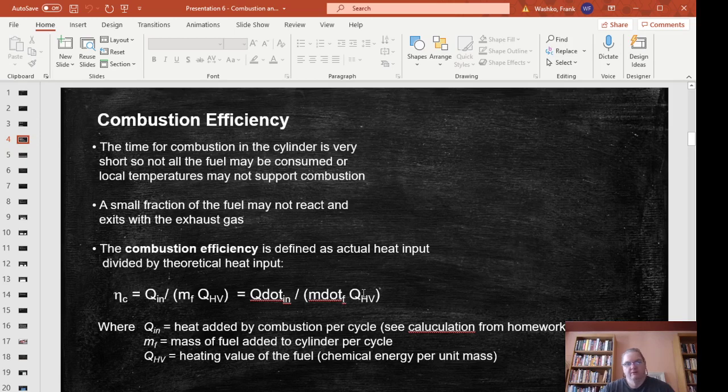So theoretically, we'd want to create an engine design that got every bit of work out of the fuel that we could. That's not going to be possible, because we're at least going to lose some of the heat out of the exhaust. Realize that you create this heat from combustion. You would get all the work out of the combustion if, when you open the exhaust valve, cold air went out, or at least air that's the same temperature as the environment. But you're putting out hot air, so you know that you're getting rid of some of this potential work.